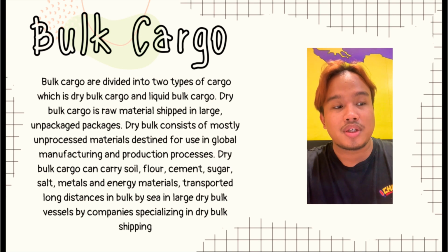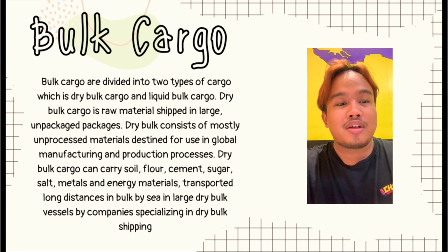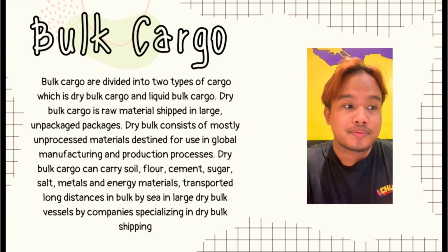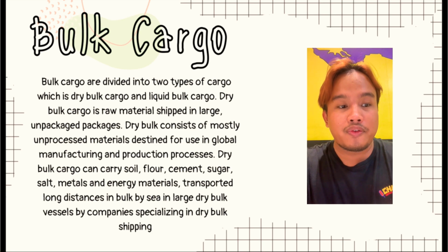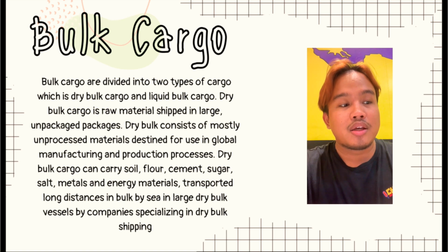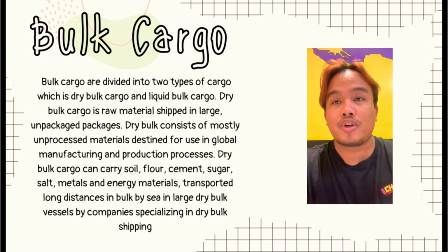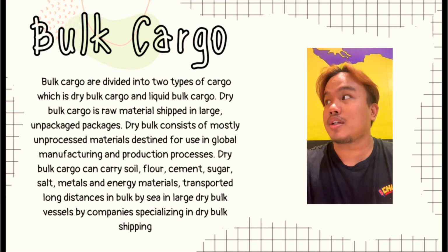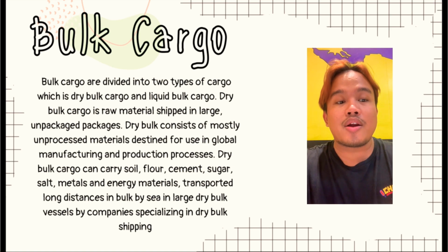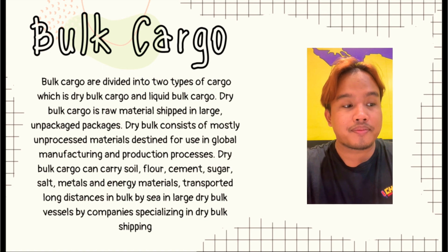After the ship arrives at the dock, the ship officer and terminal representatives will check the cleanliness of the tanker. Once they approve, the loading process can begin. When loading crude oil cargo, it is important to check for the presence of water. If found, an objection note should be made.